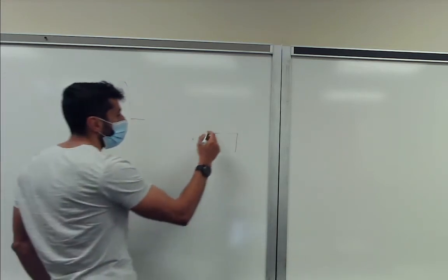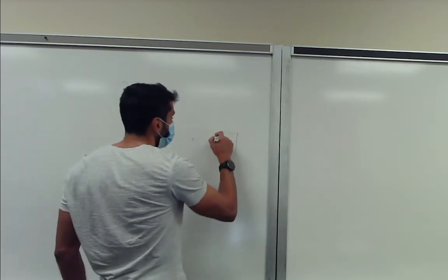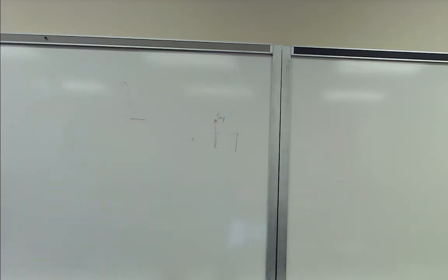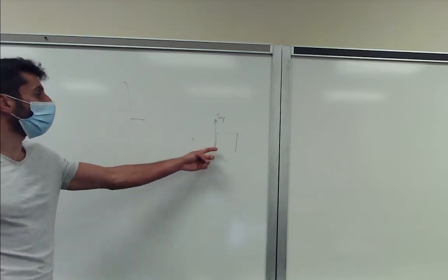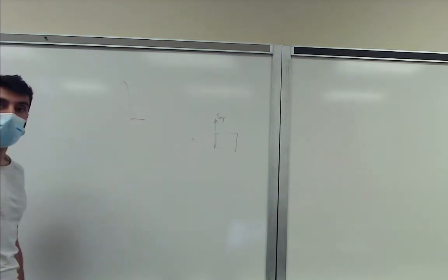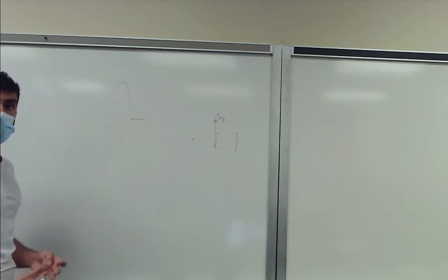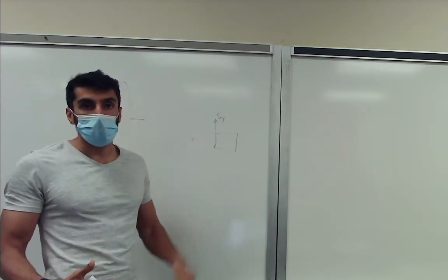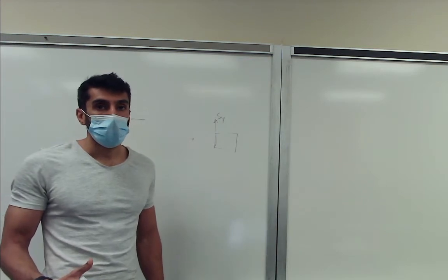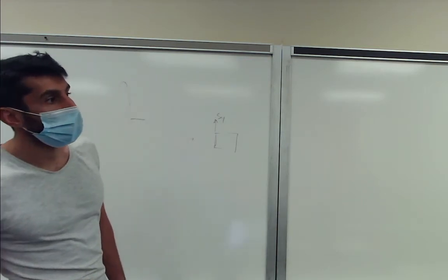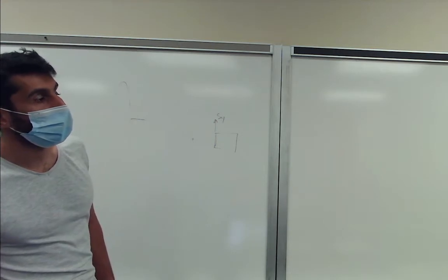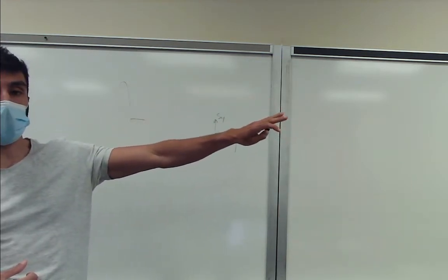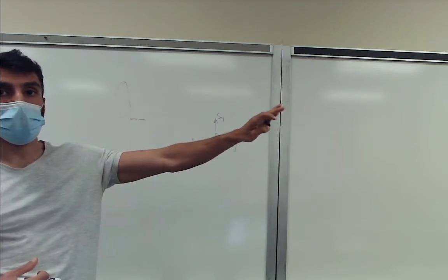If you look at the lift, it often acts on your aerodynamic center, which, to simplify, coincides with your front spar. So now you have to take into account that it's not on your shear center. So you can bend and you can twist a bit. If your design only allows for bending, then you have to come up with a solution for this. If the shear force is on the shear center, then you don't really need this shear flow and all these calculations. But if it's off the shear center, this is to determine where the shear center lies. So it gives you an idea where I can apply my force so I only get bending.